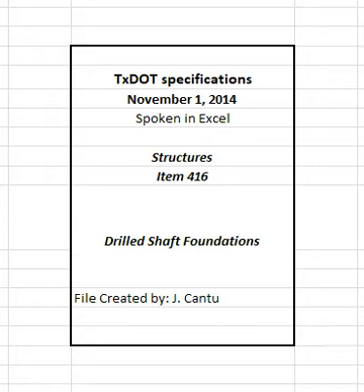Use centering devices starting at 1.5 feet off from the bottom of the cage and spaced vertically at intervals not exceeding 10 feet. Use a minimum of 3 centering devices per level at a spacing not to exceed 30 inches. Flat or crescent-shaped centralizers, sleds, are not allowed. Support or hold down the cage to control vertical displacement during concrete placement or extraction of the casing. Use support that is concentric with the cage to prevent racking and distortion of the steel.